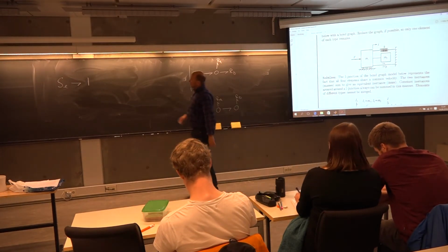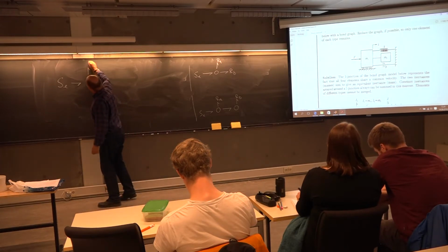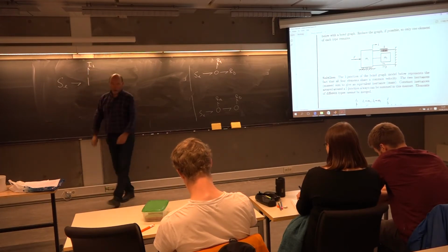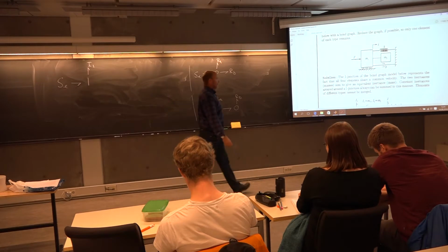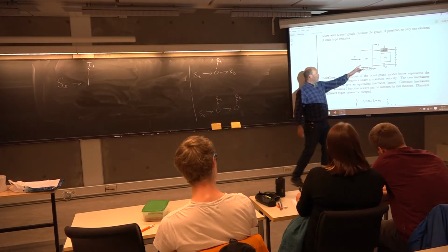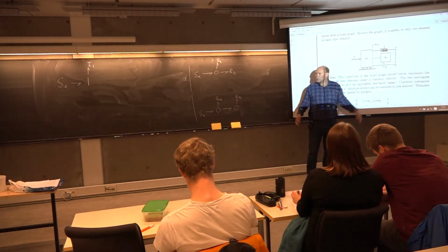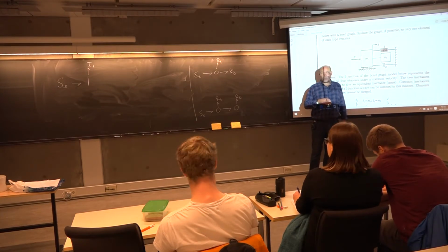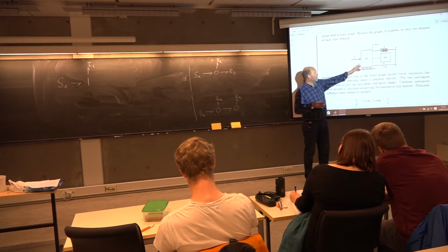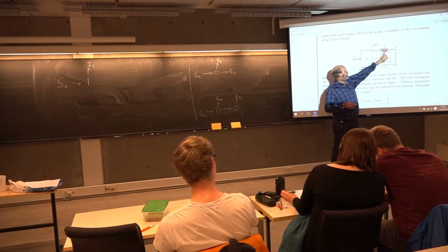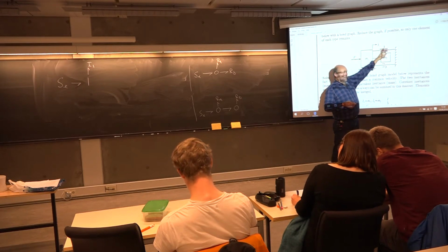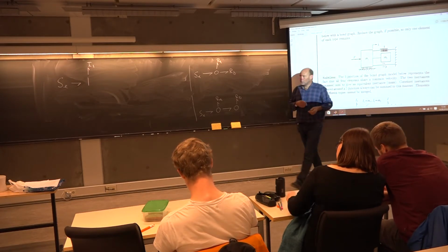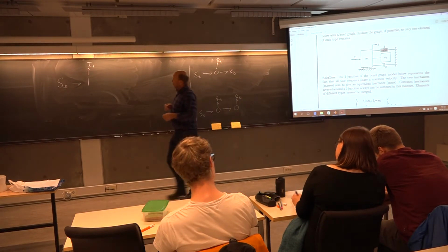So immediately I can hook up a mass number 1, I1, or small m1 if you like. Normally you will always use the generic symbols in the bond graphs. You will use I for masses or inertances. You will use C for springs. Not small m and small k, but always the generic symbols I and C and so on.